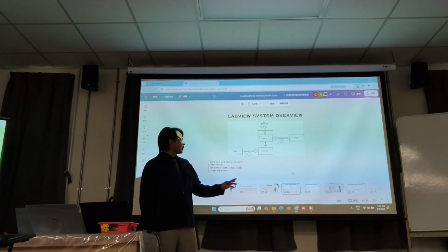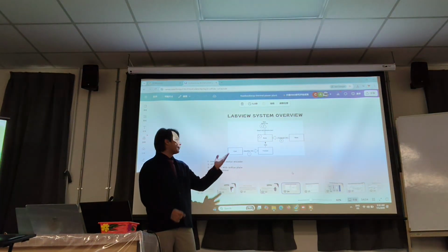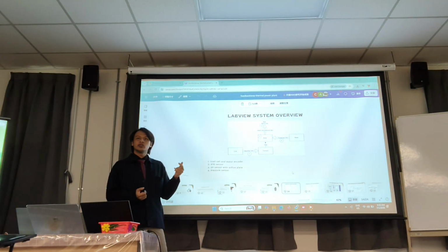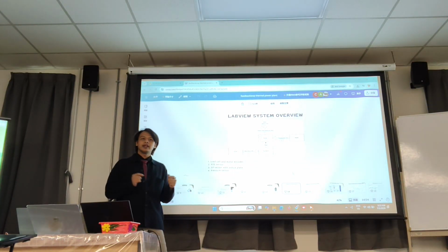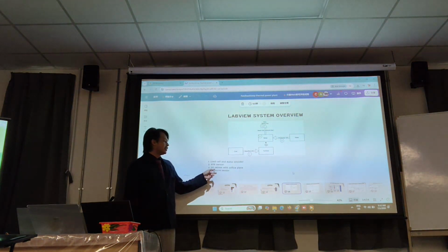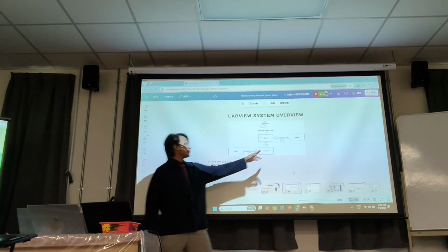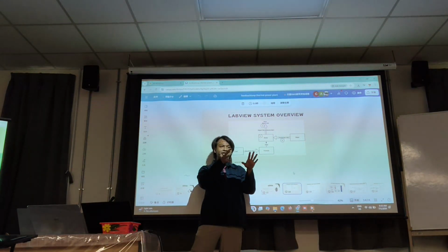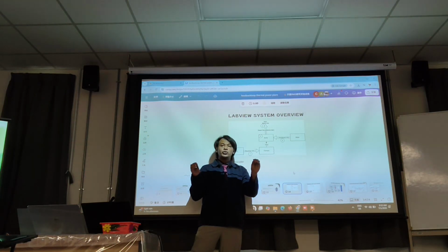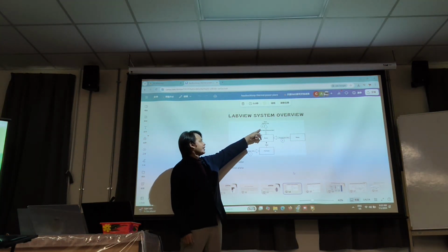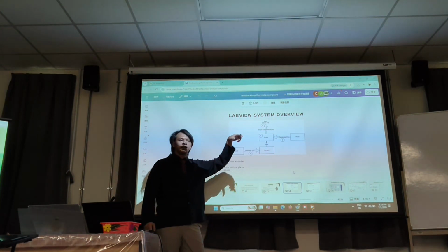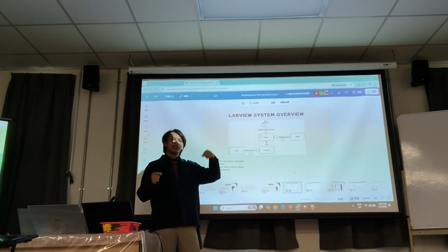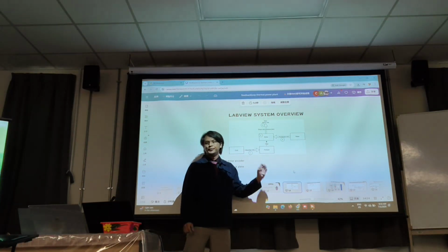So the sensors that we are using are the temperature sensors, the load cell, and also the motor encoder, just to calculate the mass flow of the coal itself, and also the differential pressure sensor with an orifice plate inside the water line to measure the difference in pressure caused by the orifice plate to know the flow of the water, and lastly the pressure sensor at the main steam line, so that we know how much pressure of the steam we achieve through all this system.